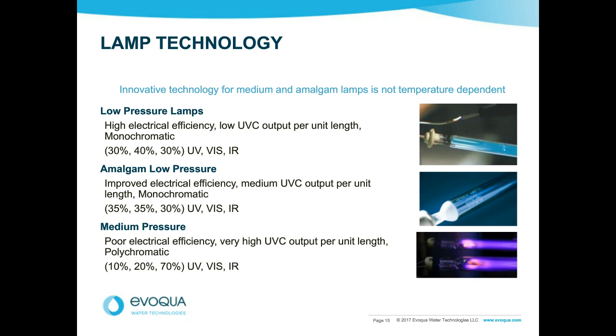Great, thank you. Next question is, what are the energy efficiency opportunities in wastewater treatment processes with UV technology, and is it cost effective? Well, okay, these are some very insightful questions, first of all. I think the energy efficiency opportunities really surround how the fluid is handled. The oldest technique is to drop racks of lamps in an open channel. That's how UV started out in North America. These open channel systems suffer from very poor hydraulics. Everything else is in a pipe. So we would only build in-pipe systems. All of our wastewater systems are in pipe. So I think put it in a pipe, that's the place to start.